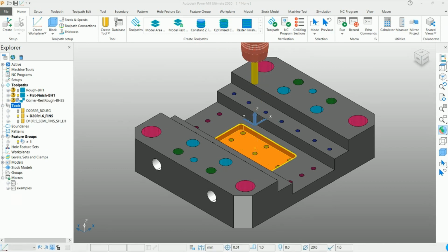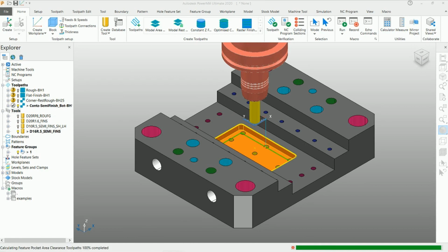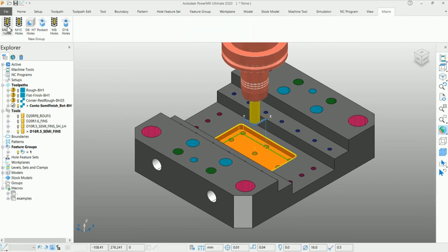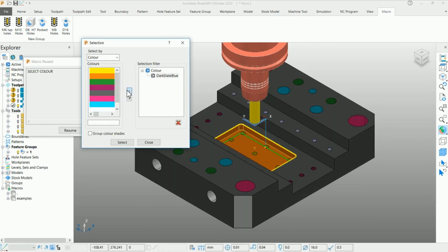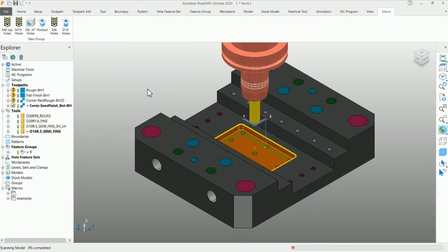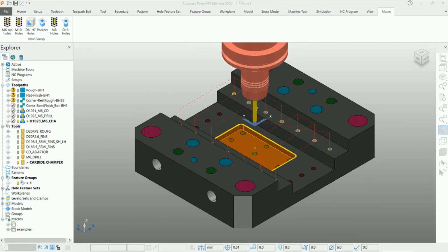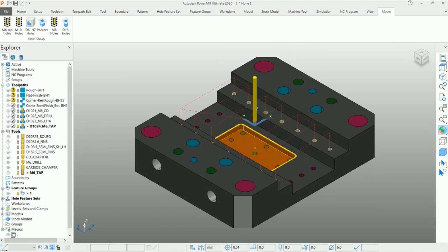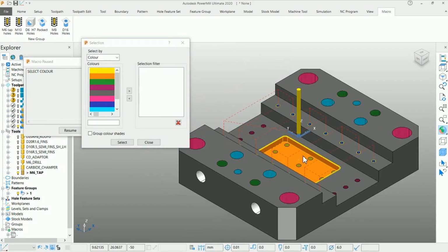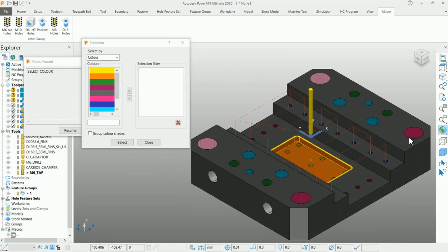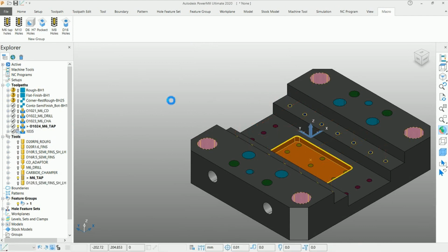Toolpath templates reduce repetitive entry of parameters and avoid human errors. This saves programming time greatly and maintains a standard across the CNC machine shop. These toolpath templates can also be called through macros for a sequence of operations in a particular feature. Quick selection filter allows the user to select whole or profile features which can later be used for toolpath calculations.